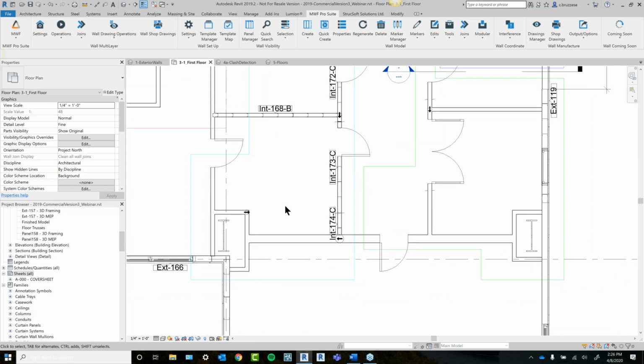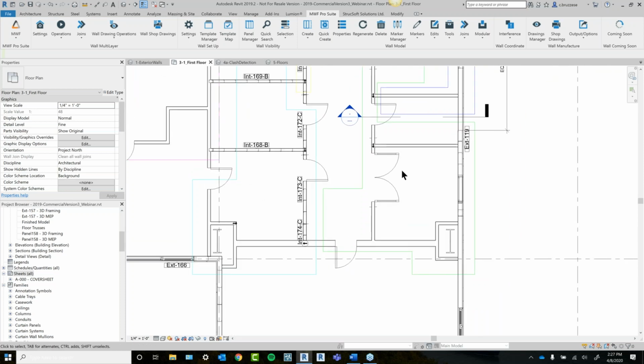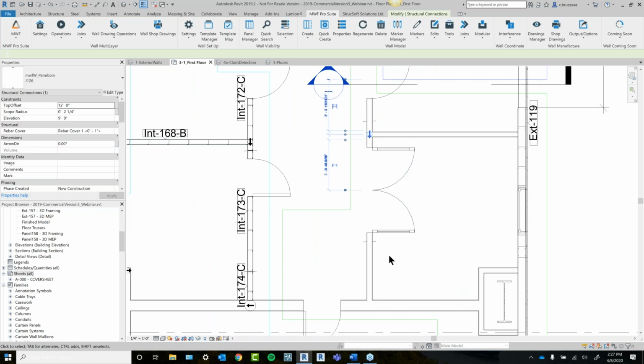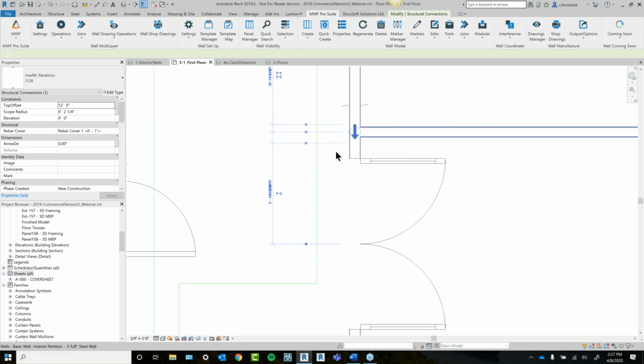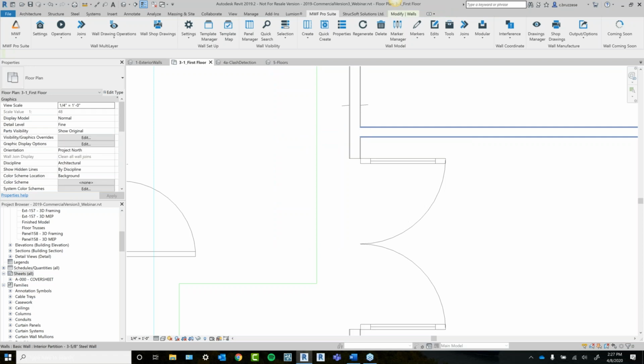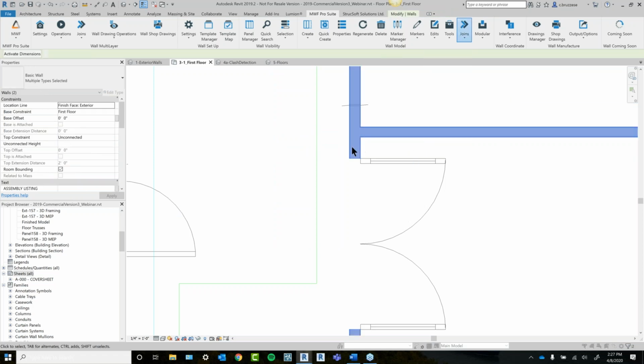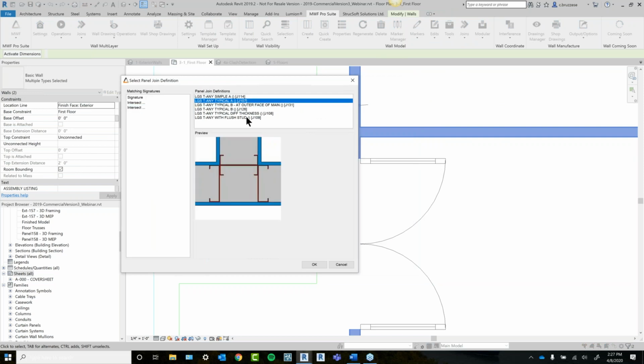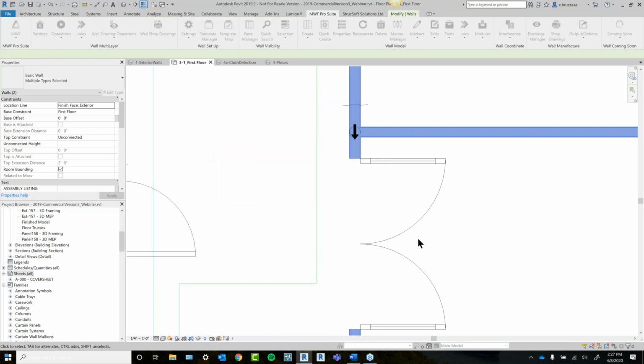So again, I definitely recommend auto joining, especially for large projects. You can do it really in a few clicks and everything will be set up. As always, if you do have to change maybe one particular connection, you can always delete and then join a particular intersection if it needs something custom. But overall, you can really maybe do 80–90% of your joins by setting up that auto join rule.